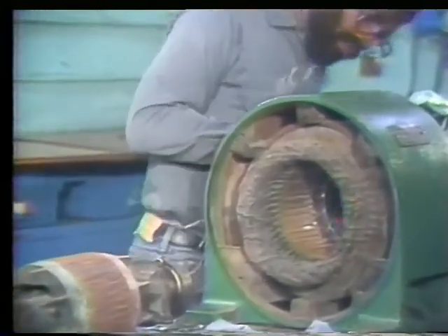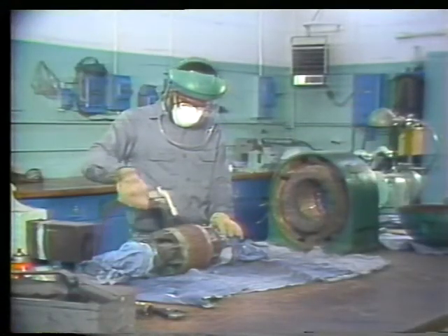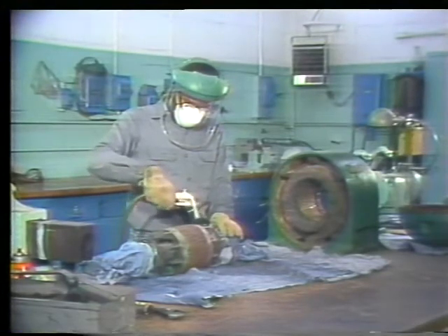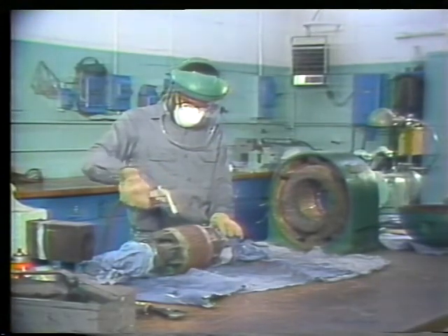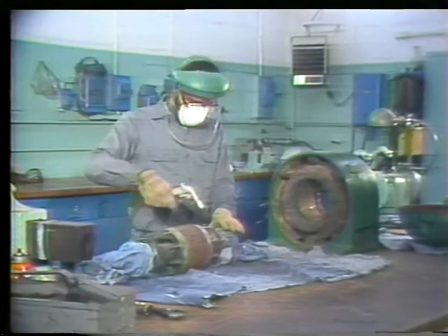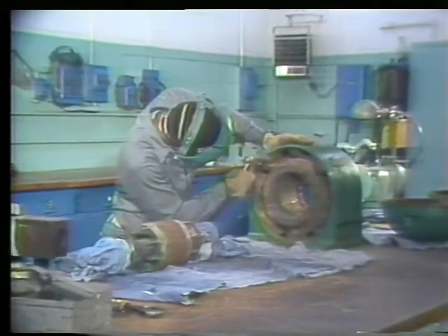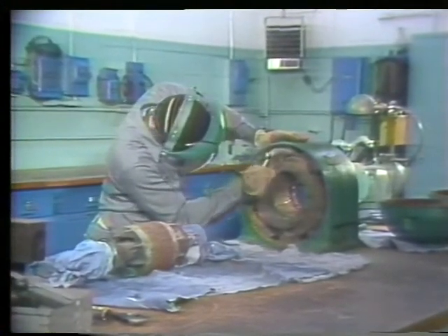When your inspection is finished, take the time to clean the motor. Use cloths to cover the bearings. Don't forget to wear a mask, gloves, and eye protection when cleaning a motor. Use compressed air to blow the rotor free of dust. Do the same for the stator. And make sure you rid it of as much dust as possible.